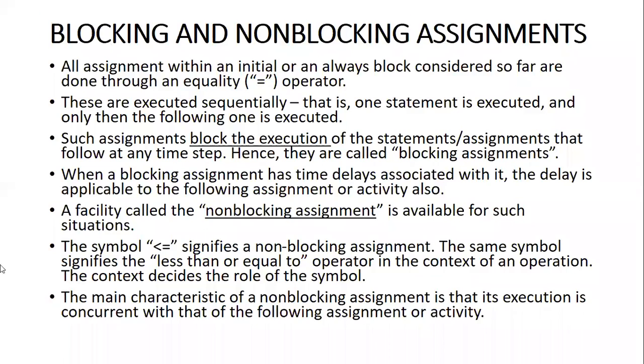Non-blocking assignment means that instead of using the equal to sign, we will use the less than or equal to operator. Anything with the less than or equal to operator, those assignment statements become concurrent within an always or initial block. This is known as non-blocking. So let us see how this is working with an example.